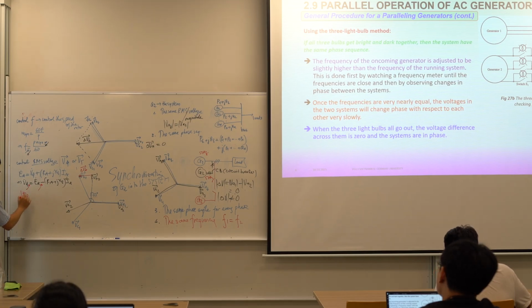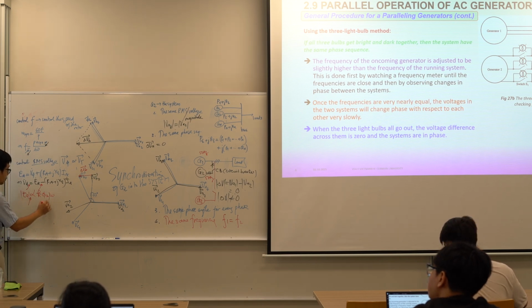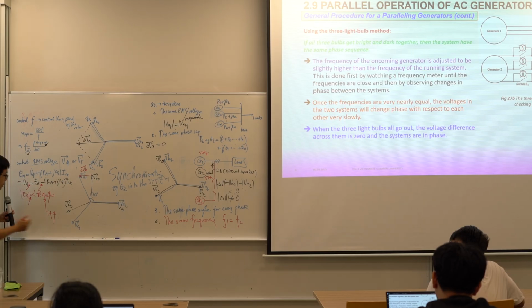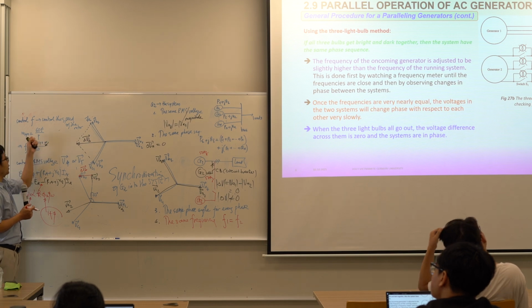We know E_A is proportional to K φ_m ω. So if we would like to increase E_A, we increase φ_m, the rotor magnetic flux. When we increase φ_m, that means we should increase the field current, the current flowing into the rotor winding. So to control V phase, we control I_F. To control the frequency, we control the speed.